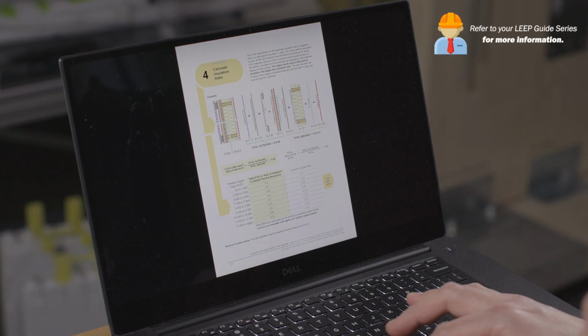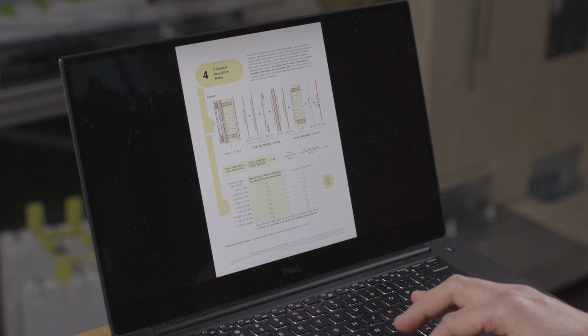Or moreover, there are a couple of different ways to look at this. The question is, how much foam or impermeable insulation do I need to put on so I don't need a vapor barrier? Likewise with vapor permeable insulation, if I've got 6 inches of vapor permeable insulation, do I need a vapor barrier? Okay, so there are 2 ways of looking at this. And generally, the higher the insulation ratio, the less vapor control you need on the inside. So the whole point of doing this calculation is to figure out where you're at. There's a minimum requirement, but there's also, call it, a building science requirement.